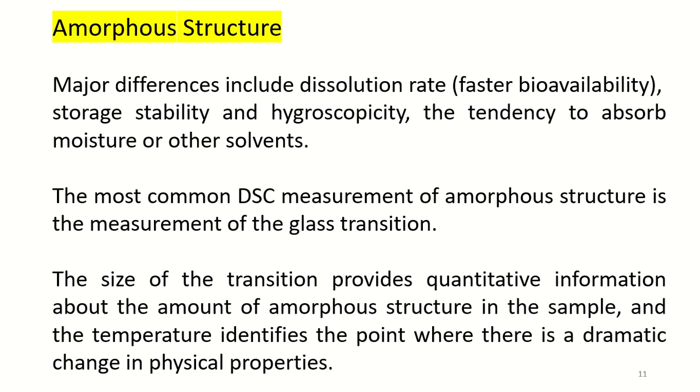Below the glass transition temperature, there is limited molecular mobility, while above there is high mobility that results in much lower viscosity and potentially much greater chemical interaction between components. Because of this, there is a general desire to store samples at least 40 degrees Celsius below their glass transition temperature.